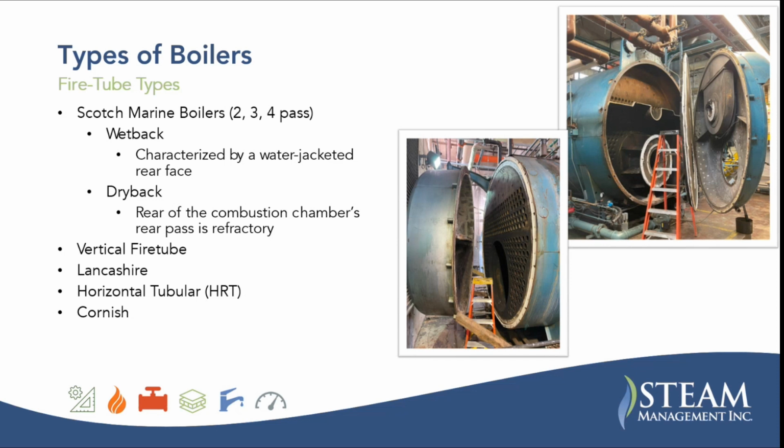Did notice a question. The pickup factor. So Bob says the pickup factor, is that for when a building goes into morning warm up, when piping and terminal heating equipment in the building is cold and creates a greater load on the boiler? If yes, then wouldn't peak heating load for a ventilated building include both envelope and ventilation load? And wouldn't good practice include keeping ventilation systems off when the building goes into morning warm up mode? What I'm getting at here is that with the ventilation systems off during morning warm up, wouldn't that effectively reduce the load significantly enough to negate any need to factor in a pickup factor?